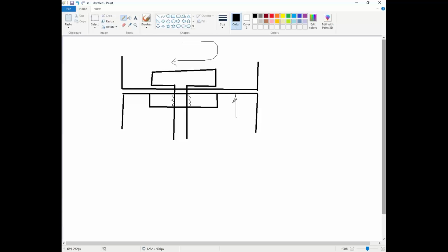But since this is the surface, that will restrict the nut. But the bolt is rotating, so the threads will try to apply force on the nut, and since the nut is unable to move upwards, the threads or the shank inside the nut area will try to expand.